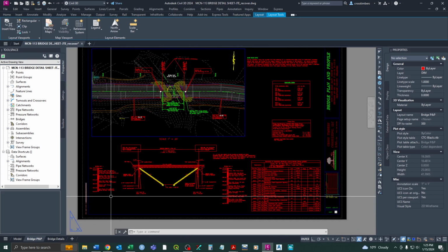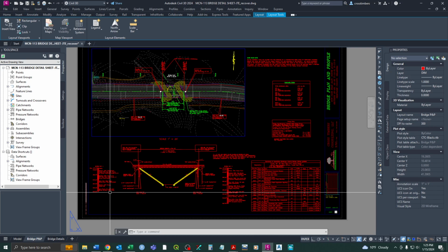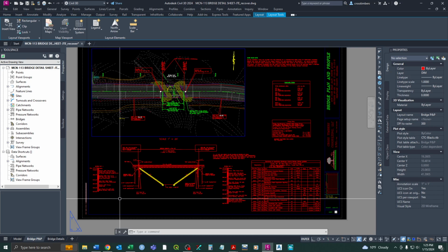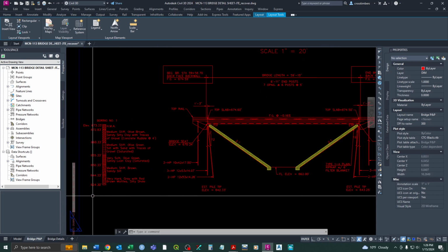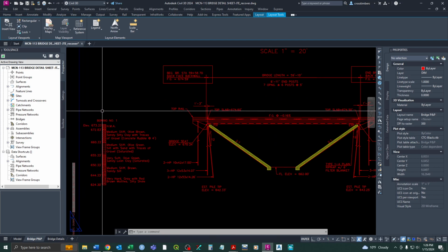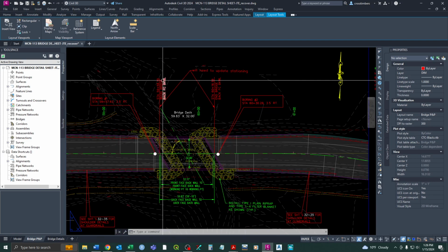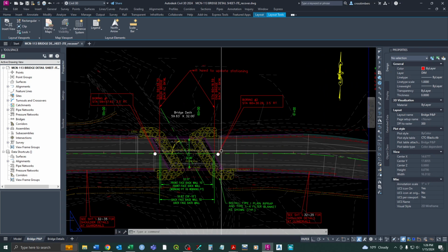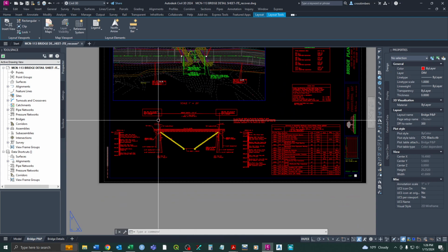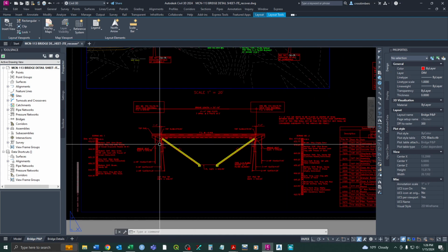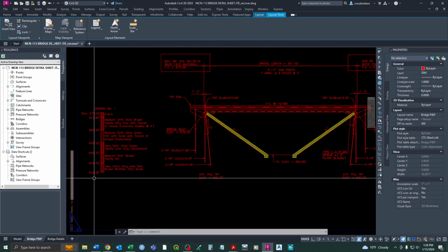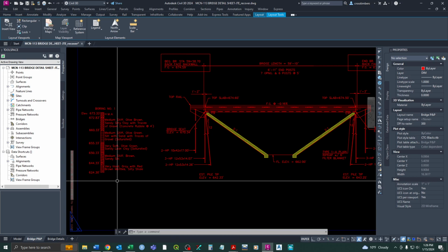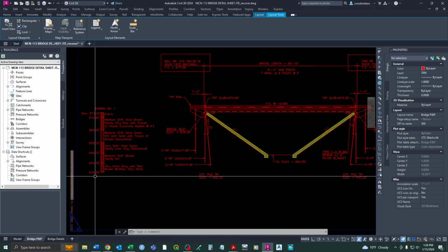So just to get started here, within this sheet, one of the first things we do is put in our geotech data. We have the geotech take borings on each side of the bridge, and this is specifically to get an idea of how deep we need to drive the piles that are tied into the wing and abutment structures. They essentially give us a soil profile of that area and then give us an estimated depth that we need to get to.